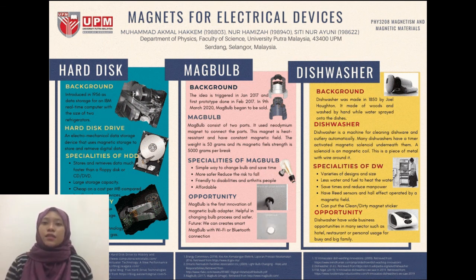This mechanical dishwasher cleans by spraying hot water between 45 to 75 degrees Celsius on the dishes, which means it only uses a lower temperature to wash the dishes. Also, for your knowledge, this dishwasher uses a magnet when the rinse cycle begins. It uses an electromechanical solenoid valve.